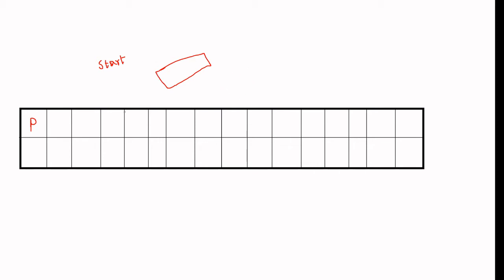So it's free running and it loops around, and as soon as the player presses start, at that instant, whatever the value there is in this register, it is stored. So the value in this register decides what will be the path that is a valid path across the game board.